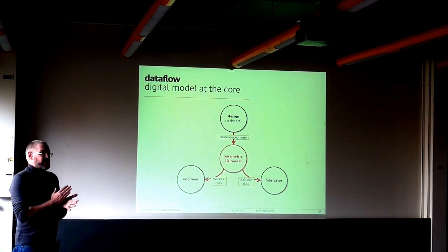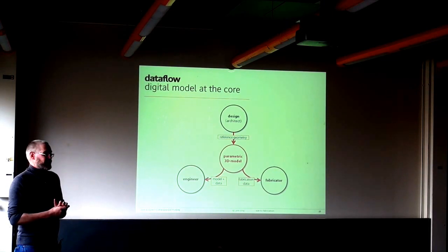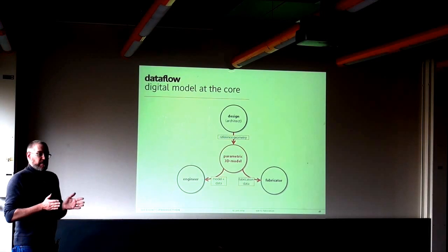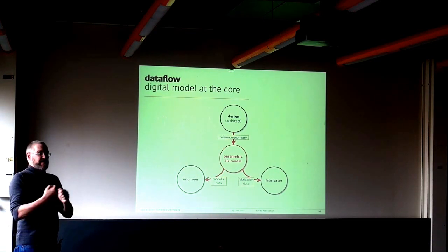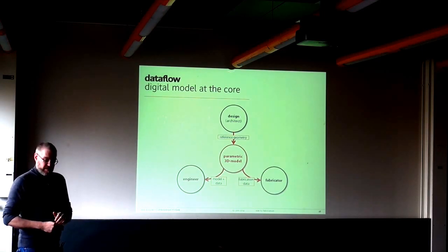In most of the projects, it's on a rather higher abstraction level than that, because we don't know the machine, and it only makes sense for very high numbers of components to really build your own post-processor to generate G-code directly to the machine. Usually we're issuing 3D models with extra geometry that would tell the fabricators what to do, and then on their side they also do some programming scripting in their CAM software to come up with the actual machining code in the end.